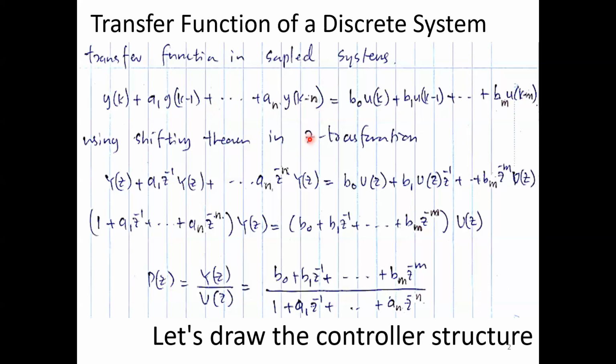So that is why we use Z transforms to get rid of this discrete nature, right? In the form of a wrapping around the discrete time, in order to get to something on a different domain, we call it Z domain. Now, when the transformation happens, Yk becomes Yz, and Yk minus 1 becomes Z to the minus 1 Yz. So you can see Yz being common with a little modifier here, Z to the minus 1, okay? So all the other delayed samples like Yk minus n look like Z to the minus n Yz. Okay, so this Z to the power minus n means how many steps the sample is delayed.